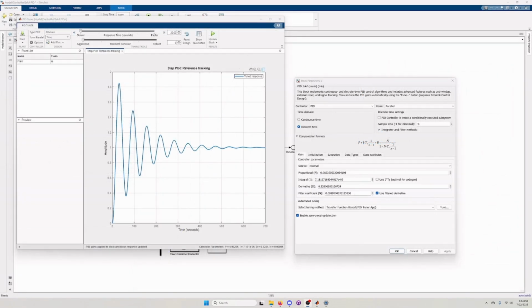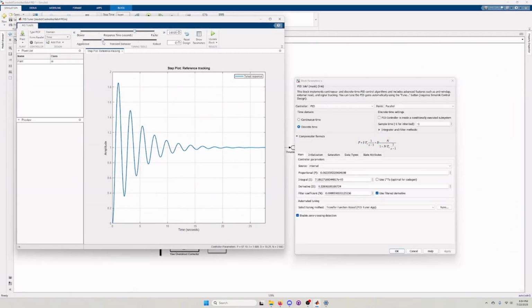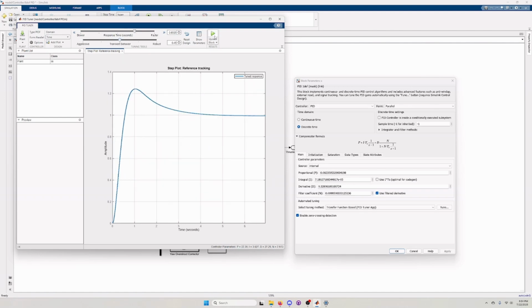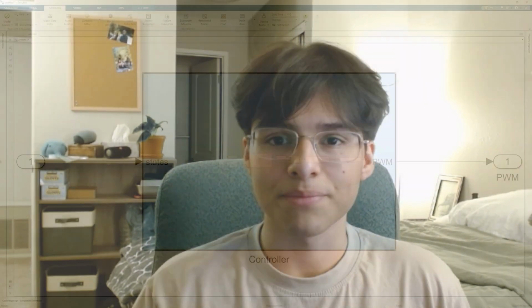With an improved dynamics model, we can use the PID auto-tuning tool to tune the 6 PID controllers to the desired step response with the click of a button and 0 trial and error. With our controller performing well in MATLAB, one looming problem remained. All the complicated signal processing and control code needed to run on the Raspberry Pi onboard computers in C++. Thankfully, MATLAB had the solution.